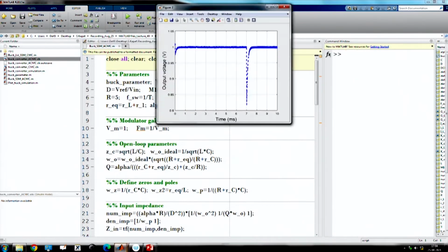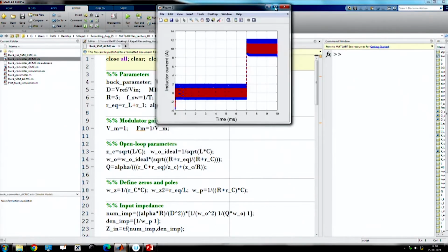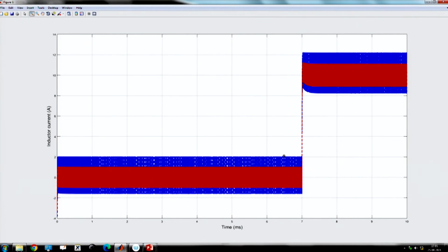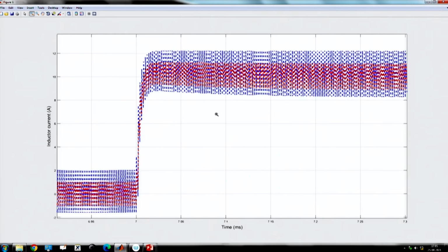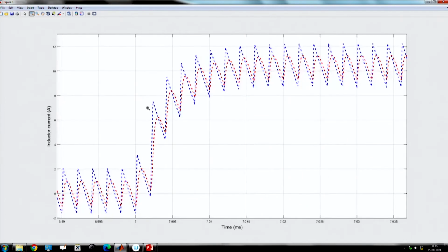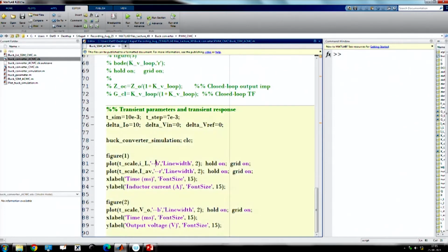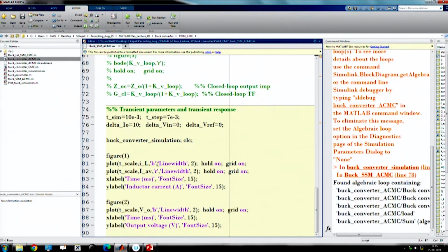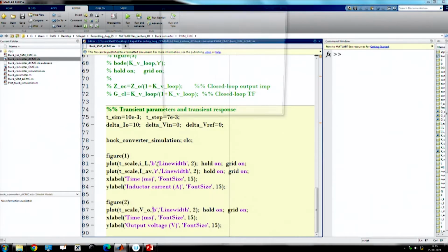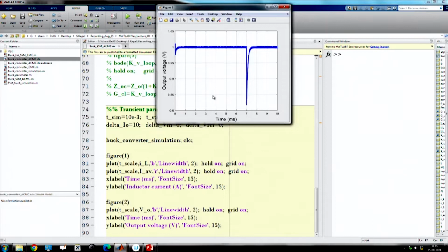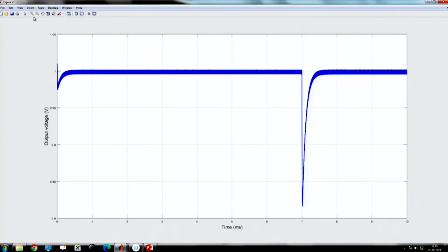So, that means by doing that we can ensure more or less stable behavior. We can achieve the stable periodic behavior. That means if we go to the solid line, what we need to do, if the current loop bandwidth is slower, we have to slow down the voltage loop bandwidth, and also we may have to add the ramp, because otherwise...